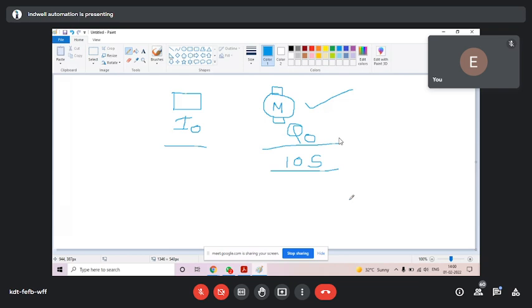Vaishali, you don't use those switches in the program. Use NO and NC there. But in your program also, I think it will get on after 10 seconds. No. See, you people are not understanding. Q0 should be on for 10 seconds. What does it mean? It means after 10 seconds, Q0 should be off. But most of you are doing Q0 on after 10 seconds. Not correct.